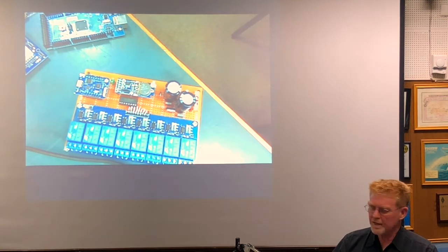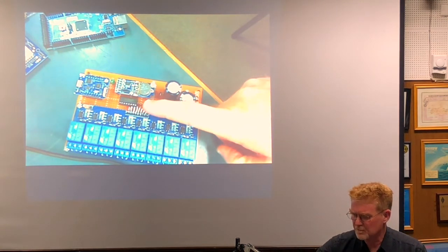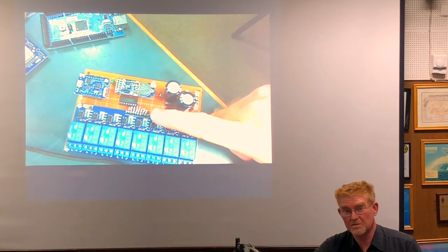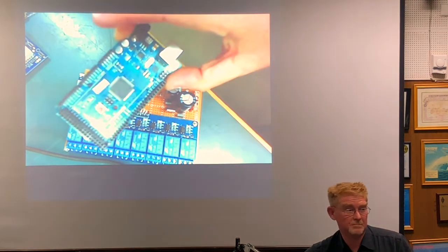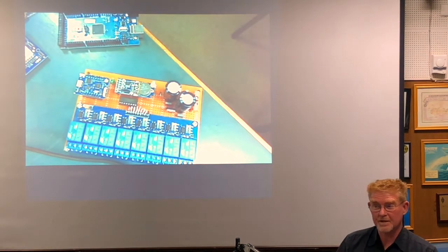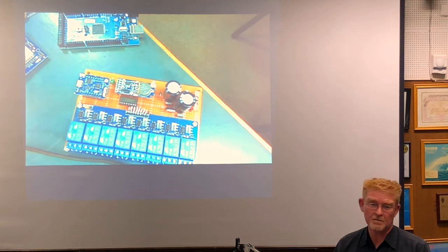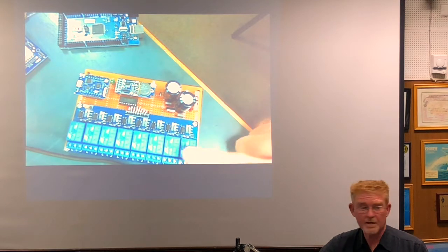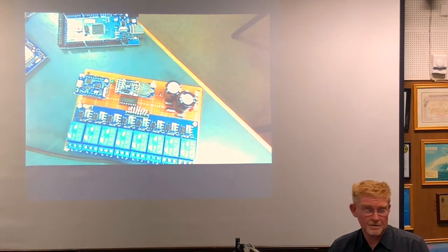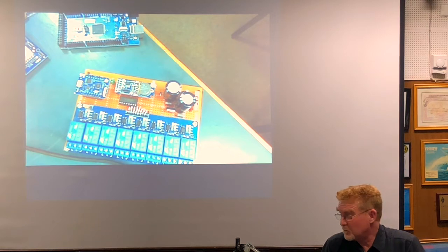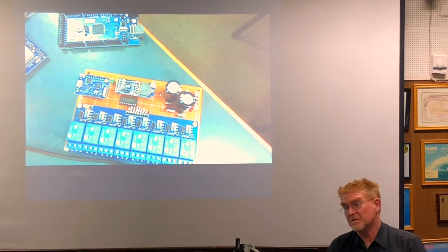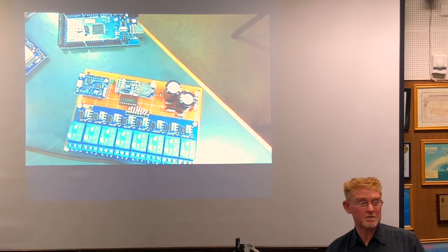I think the way that the I/O expander works, you have a maximum of 8 of them connected in series. You have to pick a different chip. That's 64 bits of I/O, which is more than this guy can do. Not as fast, but again, it's all about maximising the I/O and picking the right chip for the job. That was $2 or $3, I think, but not terribly expensive. The relay board here, $12 from eBay. All the hard work is basically done. It's download the example libraries for the internet, look at people's code examples, work out how my idea fits using those building blocks, and go off and do it.